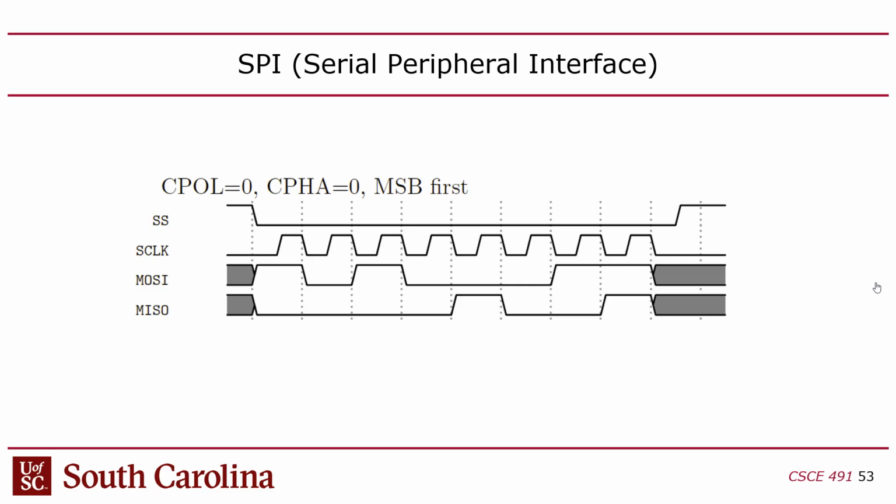Now you might say, wait, why do we need 2 signals for that? Why not just have 1? Well, one of the things that's crazy here is that the first time the data is changed, there's actually no falling edge on the clock. Normally the data is changed on the falling edge, right? Every one of these dotted lines shows where the data changes and it corresponds to the falling edge. But the first time, there's an exception: there's no clock edge the first time the data changes. So the data has kind of a head start on the clock here.